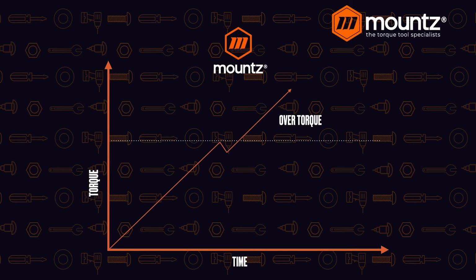And so while the click wrench is a good wrench that can be used in a lot of applications, if you have a critical type of application, or you are seeing inconsistencies from operator to operator in the use of a click wrench, that may be the issue. And so this kind of ties back into the human aspect of what we normally would consider their involvement into the consistency of torque that's being applied.